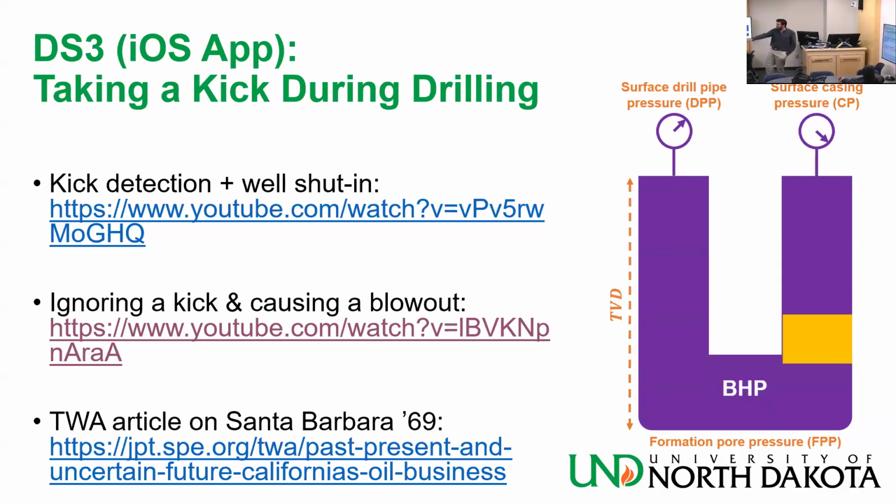So you may have shut in the well and you think everything is okay, but the kick is migrating up. It's migrating and it's getting bigger and bigger as it goes up. It's basically bringing reservoir pressure up to the surface. And this is very dangerous. It creeps on you if it's gas.